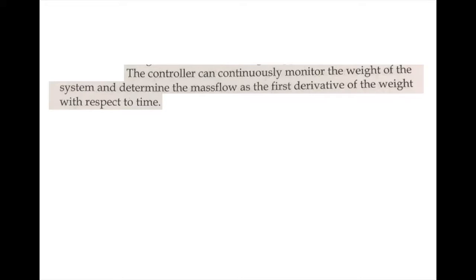I worked for Procter & Gamble for 10 years, and their strategy is to invest a lot of money into automated equipment. In our case, we would always use a control system such as Wonderware. It was in Wonderware that we would actually be reading most of the information that came from the K-tron. It's only during troubleshooting and setup that we would go to the K-tron local controller. But their point is that the controller can continuously monitor the weight of the system, and that is what's needed to understand the loss in weight.